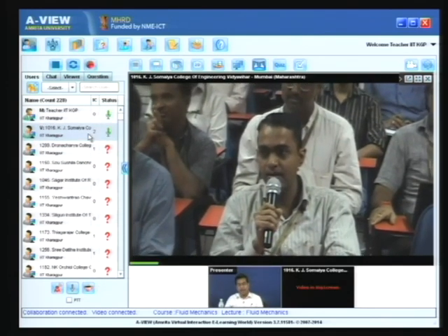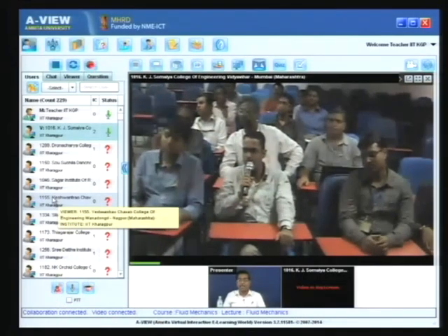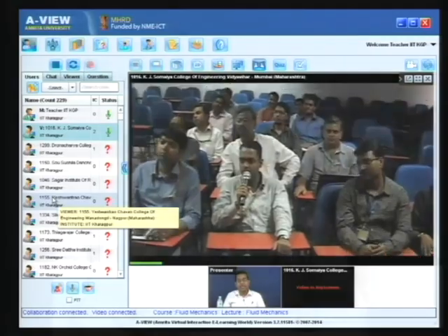I will tell you the physical significance of degree of reaction, as I explained through the examples of the paddle wheel and the lawn sprinkler. Degree of reaction means that in a reaction turbine the static head is utilized to develop the power. So, how much static head will be utilized out of the total head in the turbine, and how the kinetic head and the pressure head are distributed at the inlet to the turbine, all depends upon the range of flow and the range of head available. So, one cannot say how much reaction will be required; that is manifested through specific speed.